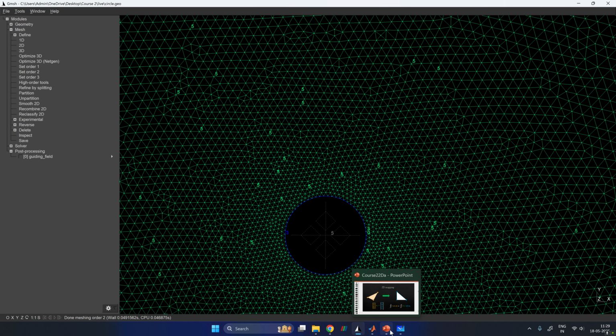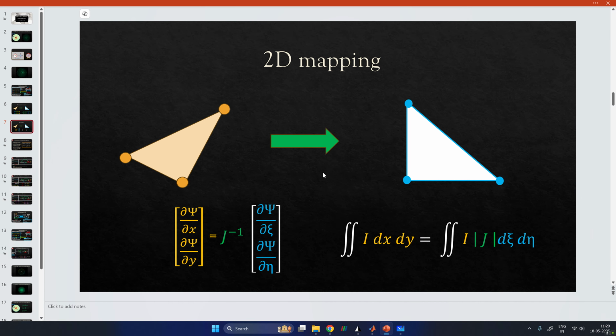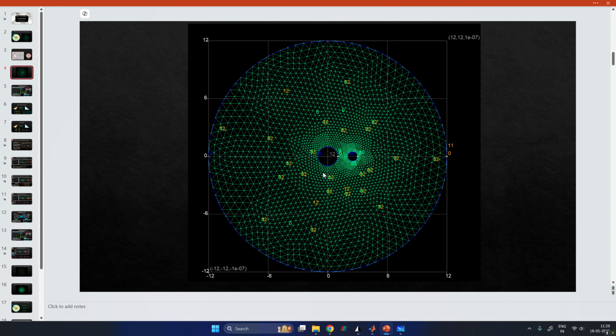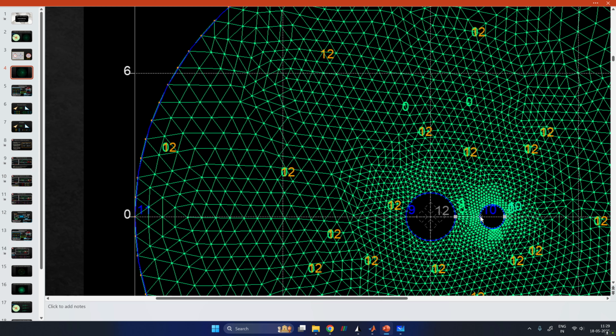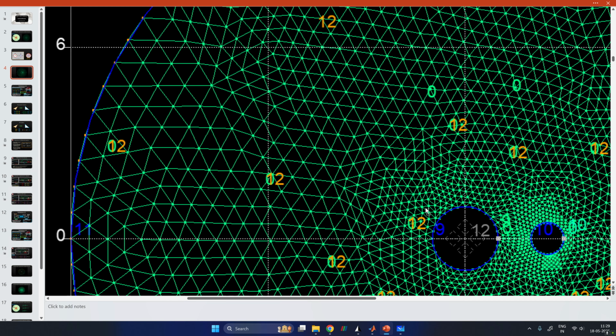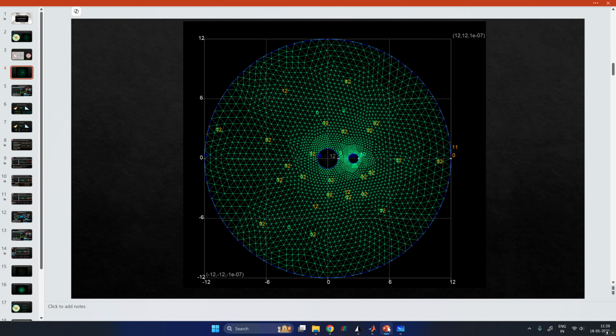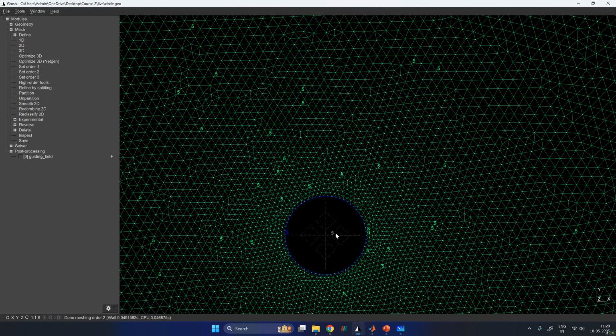If we look at a mesh which has slightly more complicated features like this, you can simply see that there is some stretching happening here, right? So between these two, whenever you have a complex geometry, you can see that the mesh will struggle to model this geometry. So we need to make sure that the mesh is correct, and this obviously also depends on the problem as well as on some very straightforward metrics which are the same for any kind of problem.